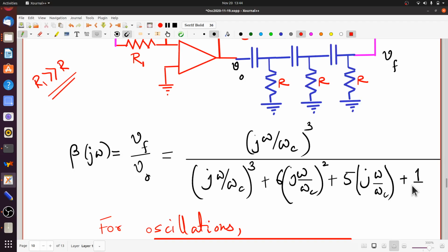The unity gain buffers that we had introduced in the previous circuit had the advantage of isolating input from output for each RC stage. So you could just take the transfer function for one RC network and just cube it to get the final answer. Here it has to be calculated with more care. However, the final result is pretty easy to interpret.